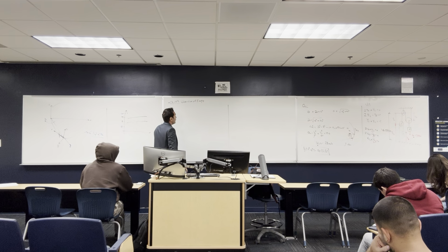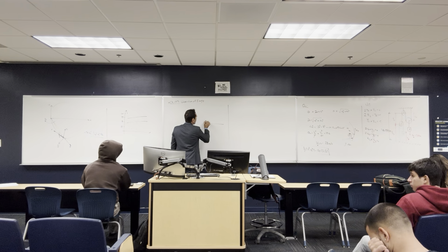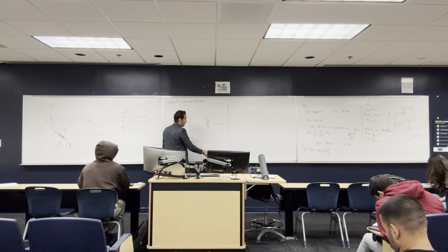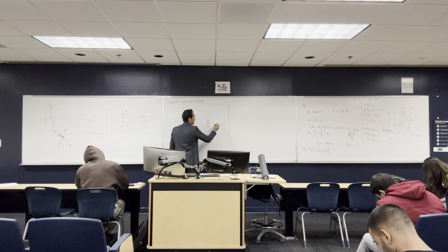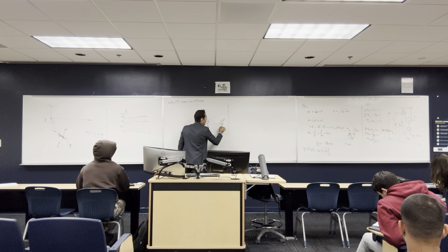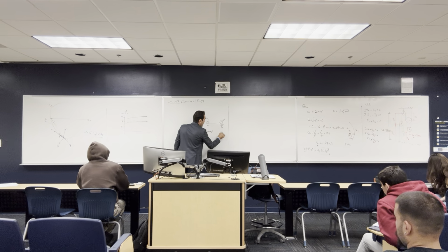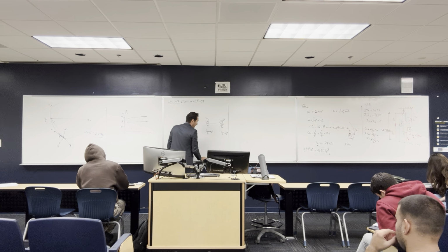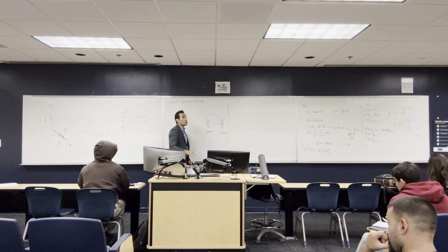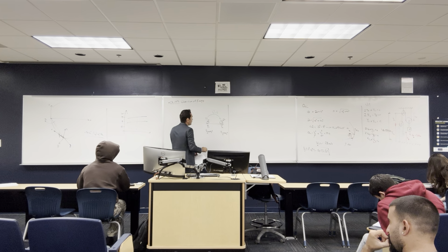Alright, for conservation of energy, if you guys remember, if I have a body, and this body is moving with a specific velocity v1, it's gonna have a kinetic energy T1 at this position. And if you apply some external forces, and somehow this body under these forces got to this position with v2, it's gonna have a kinetic energy T2, and this kinetic energy is half mv1 squared, and this half mv2 squared. To bring the body from here to here, you have to exert some work to change the body's energy. So this is the work that you exert, the work from 1 to 2.